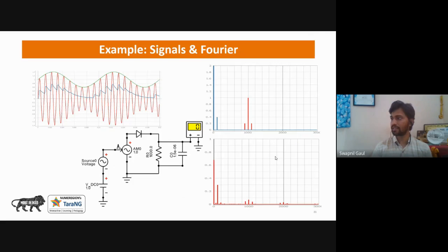And in communication systems, in the morning I had demonstrated amplitude modulation, but here we are doing the same thing, but I added some DC voltage to shift the envelope upside, and the rectifier circuit that we designed, we just kept as a demodulator circuit. So here we can see how the blue graph, the demodulated signal, will look like.